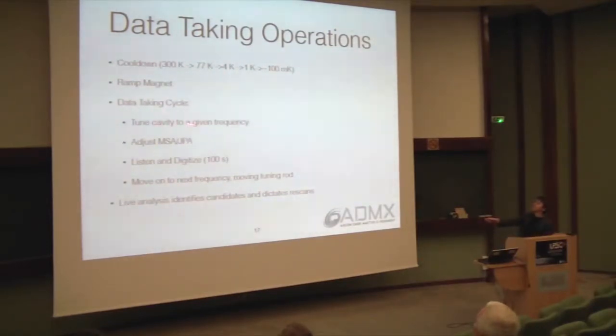So the cavity is tuned to a particular frequency. We check our coupling and Q factor through S parameter measurements. We optimize, adjusting either the SQUID or JPA, whichever we're using in the given frequency. And then we listen and digitize for about 100 seconds. After that, we move to the next frequency, looking in a new spot. While this is all happening, there's a live analysis that's constantly checking for a possible candidate, and that would dictate to go back and rescan.